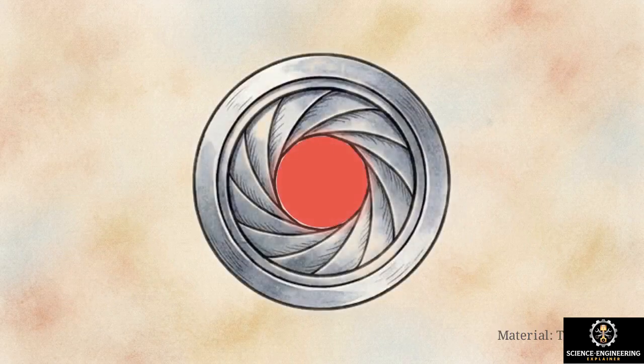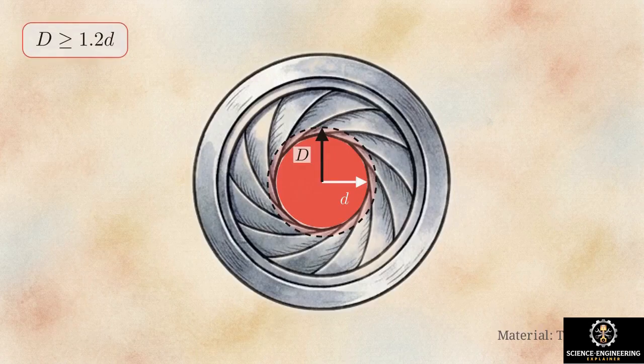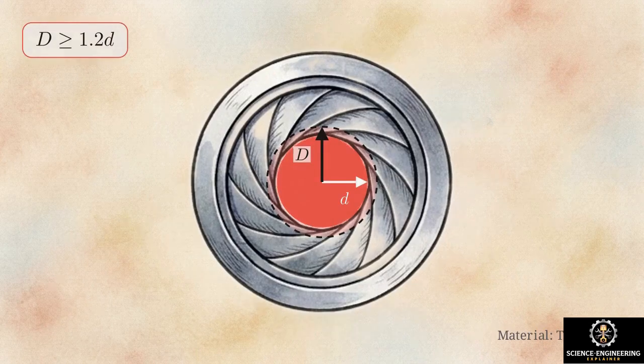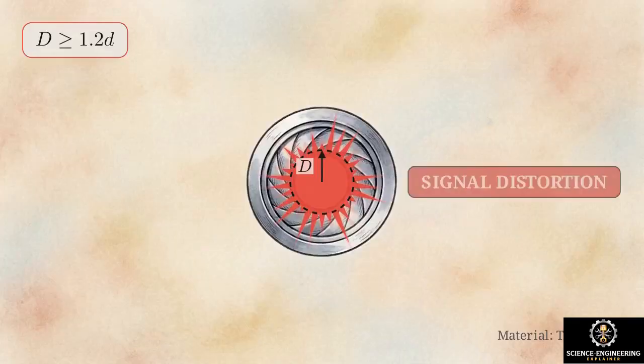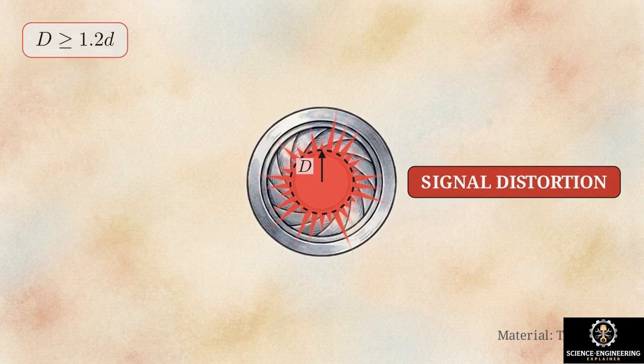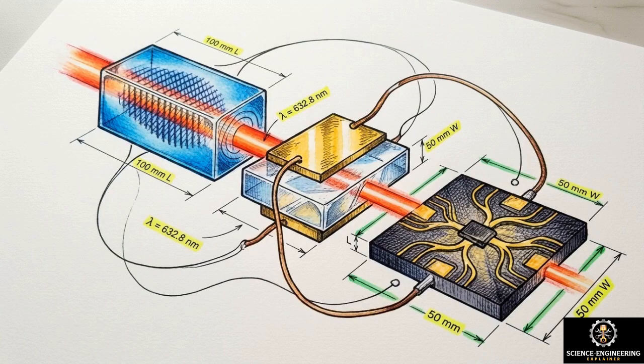You must also size the physical aperture correctly. The effective aperture of the device needs to be 1.2 times the diameter of your incident beam. An oversized aperture wastes acoustic power. An undersized one causes incomplete edge diffraction and disrupts the beam quality. Acousto-optics provide long-term stability for industrial applications, but they require rigid beam sizing and wavelength planning during the initial design.